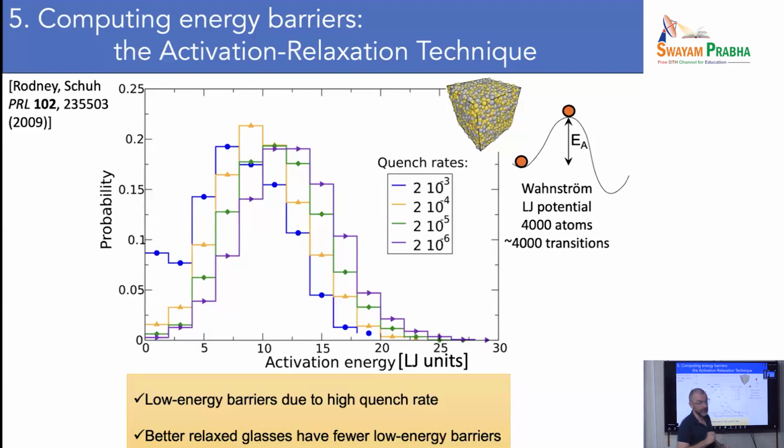If I ask you that, you're going to have at least two problems. The first one is that the system being completely disordered, you don't know what is the final state beforehand. It's not like a vacancy or a dislocation where you know that the vacancy will go from one atomic position to the next. In a glass, there are no such reference atomic positions, so you don't know beforehand what the final configuration will be.